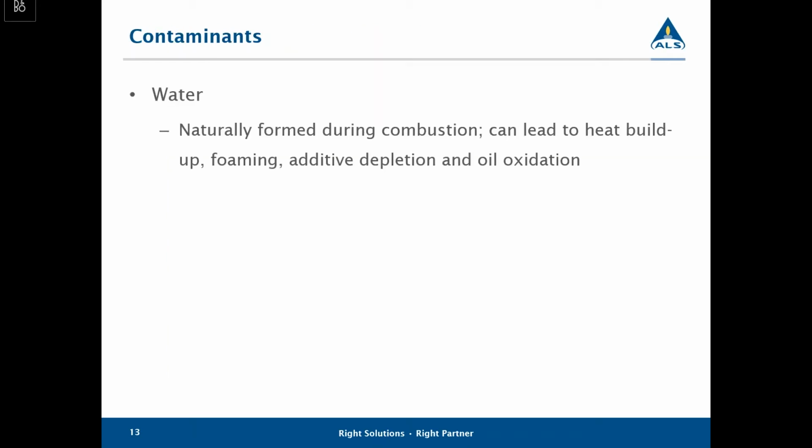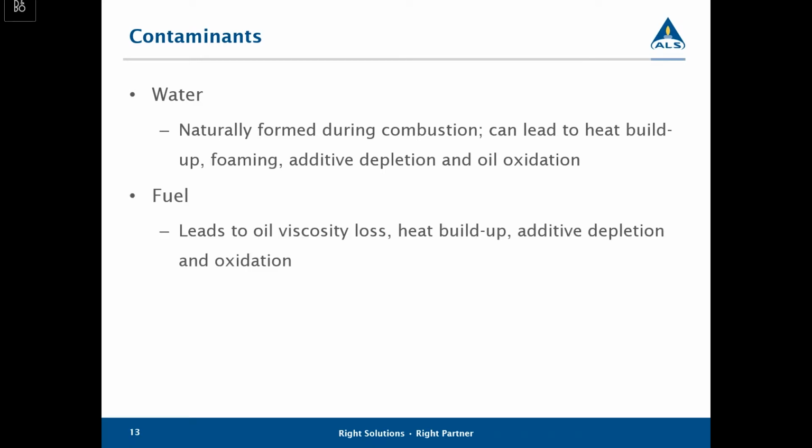Some contaminants that you might see in your engine is water, naturally formed during combustion, but it's kind of a harsh environment, so it might evaporate, but it is formed in that combustion process. If it does get into the oil, though, it can cause foaming, additive depletion, and oil oxidation, as well as impeding how that oil can lubricate the equipment. Oil and water, they don't mix well.